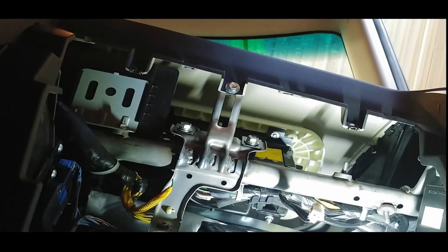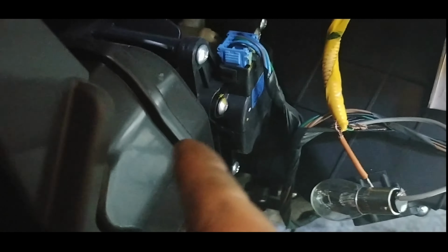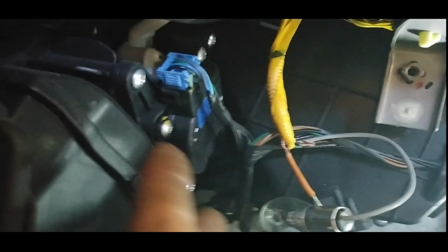We're going to pretend this connector wasn't broken, and do the same testing that I did on the Rondo. We're just going to hook a light bulb in between and give it a resistance value, so basically we're substituting the load. I connected my light bulb, so now we're going to cycle the key to reset the system and see if we're able to get a reading in the data.